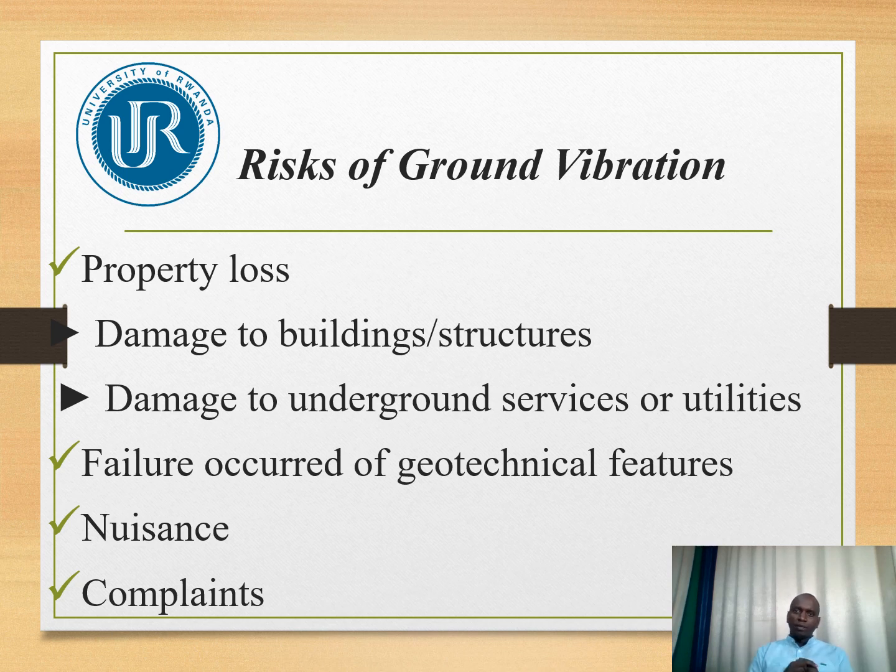The people who are always nearby are always complaining, saying our houses are being damaged by the ground vibration from the blasting operation. There is a regulation stating that the infrastructure nearby the blasting area should at least be 500 to 700 meters far from the blasting area.